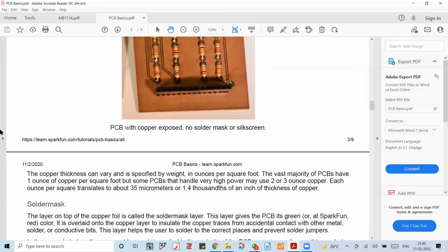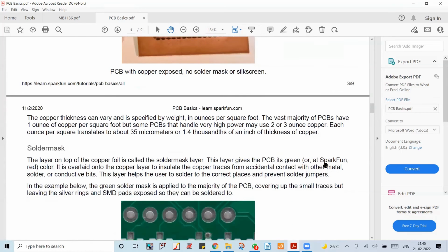So in such a scenario, normal laptop power consumption, battery consumption will be like 70 watts, whereas a gaming laptop will be 120 watts. So there the current will be double. In such a scenario, if you give the same design with copper thickness as 2 ounce, then the normal laptop charger design can be used for a gaming laptop. Understood, right? Yes, ma'am. So that is the only difference. Got it, right? That's the reason we go for 2 ounce copper.